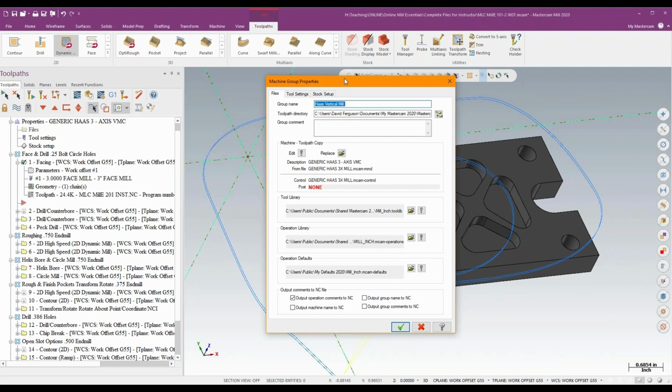When I select and run a toolpath in Mastercam, fields are already populated with values. Certain things are turned on, certain things are turned off. It just depends on what you've got and what you're working with. So if I want to have those values be closer or similar to what I'm using, without always having to change them, without always having to take that 50 thou off the wall or off the floor, or to always use a profile entry, my comp is always set to wear instead of control, or I'm using an arc filter all the time, I don't want to have to constantly be changing those values every time I write a toolpath.